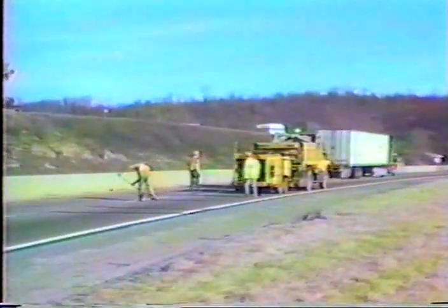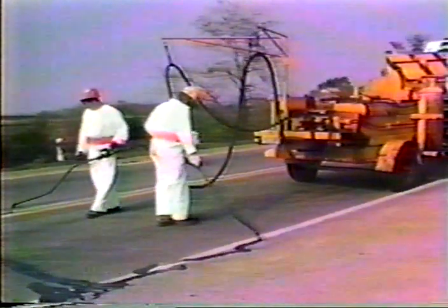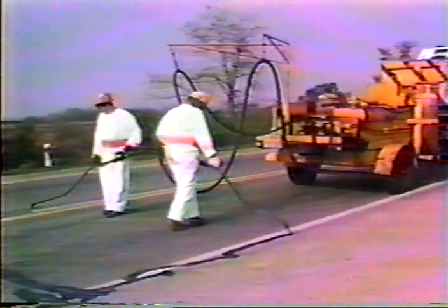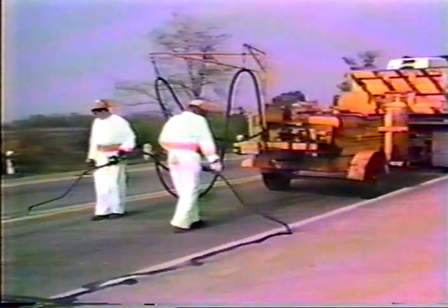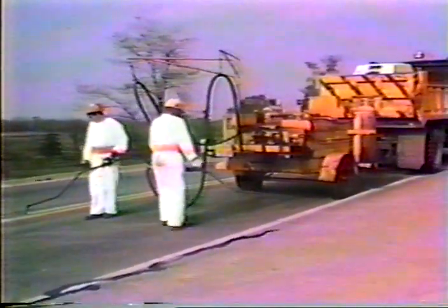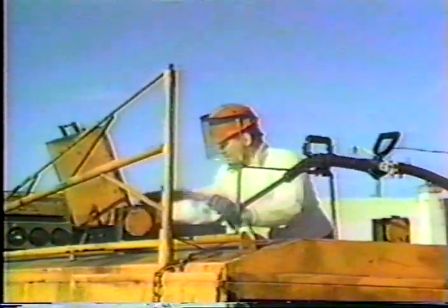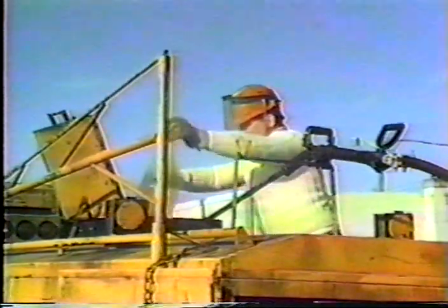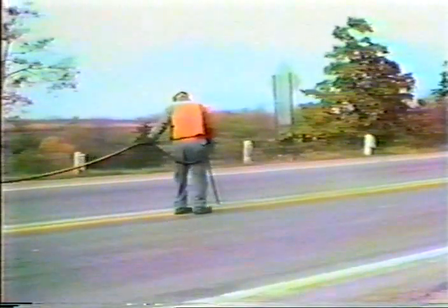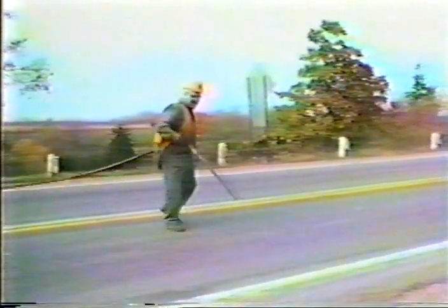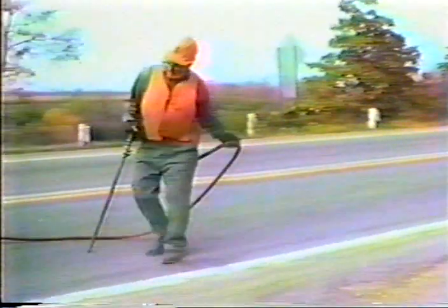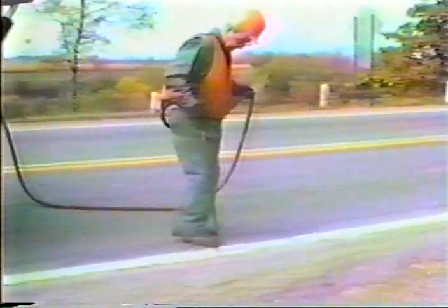Personal protection equipment must be used at all times when working around the hot sealant. That means gloves, long-sleeve shirts, and safety glasses must be worn by the person using the wand or charging the kettle with asphalt cement or an additive. The person using a blow tube or hot lance, as well as those working nearby, must wear safety glasses.